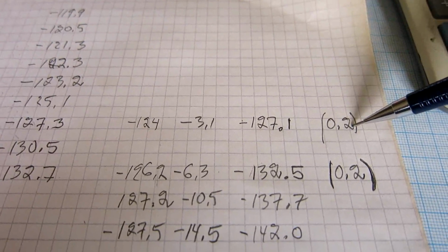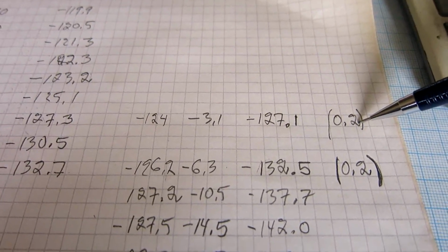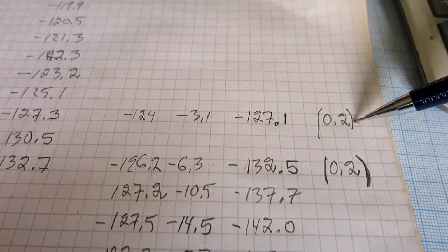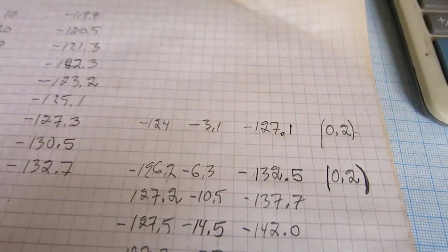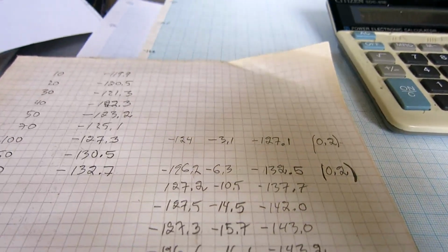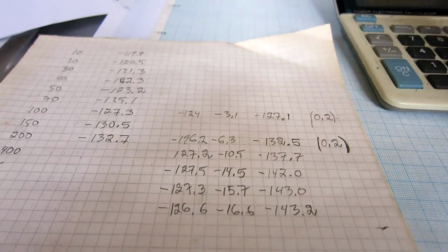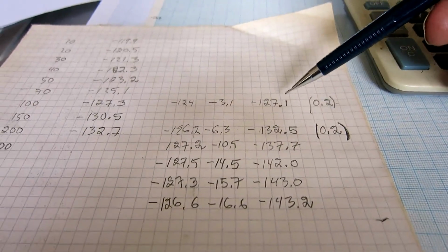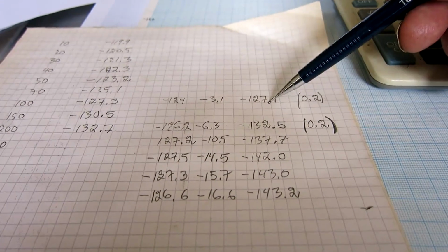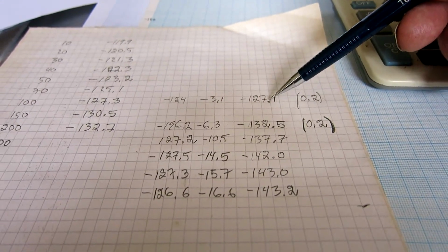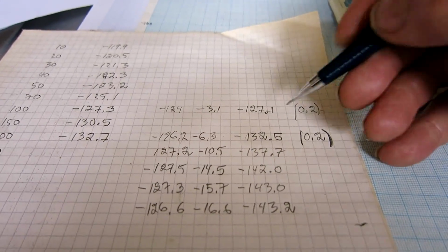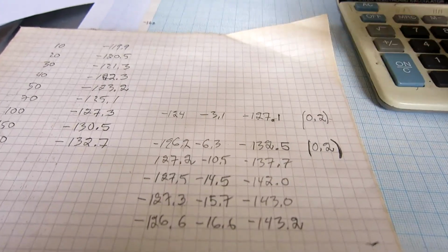This is the table from the signal analyzer graph, and here is what I found from the correlation measurement, and the values differ by 0.2 decibels. This is an error because now I'm measuring the sum of the AM noise and the phase noise, and I know that they are equal. So there is an error in the software that I have been using up to now.